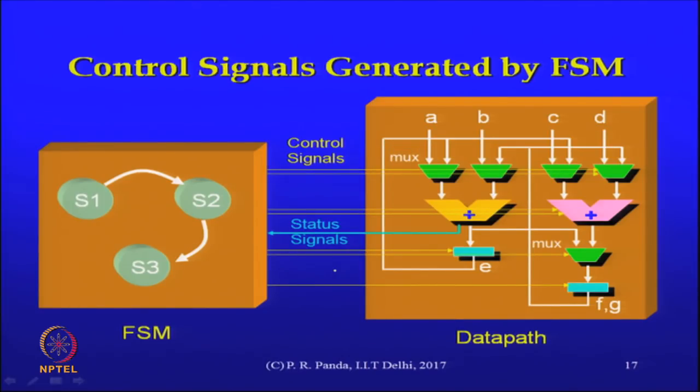So, these control signals would be generated by the FSM, bringing us back to that picture. Hopefully, this high level overview gave us an idea of what the steps are and how they help us in getting closer to the hardware. Of course, that FSM is still symbolic. This is not quite a netlist. This part is of course closer to a netlist.